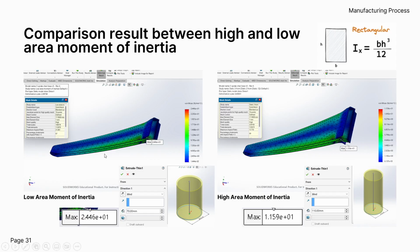So you can see here in these two examples, other than force distribution with the tapering, with a more exaggerated thick to thin, you can see this height is only 70 when compared to this, which is 110. You can see the difference in MPa. This is 24; this 0.1 means to the power of 10, so you need to move one decimal point here. So this is 24 MPa for 70 mm. If we increase it just by 40%, it basically divides it by more than half. That is the power of the formula. So you need to understand the formula, and then you'll be able to better create your own design.